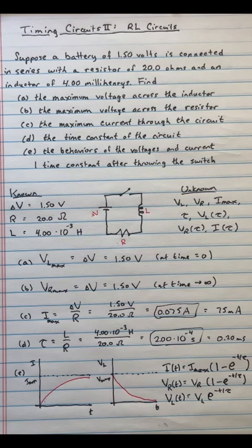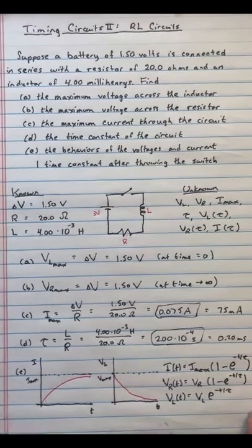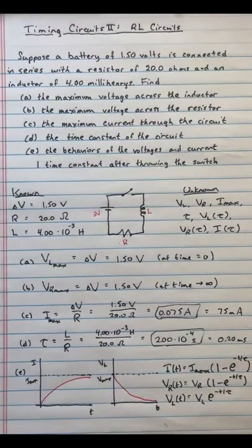If, on the other hand, you talk about the current through the coils or the rest of the circuit, or the voltage across the resistor, that's 1 minus 0.368, or roughly 63% of its value going up. Again, we've talked about this in a previous video. So I'll let you go ahead and do your calculations on your own to show what the specific numbers would look like, but these are the formulas that you would use to make those calculations.